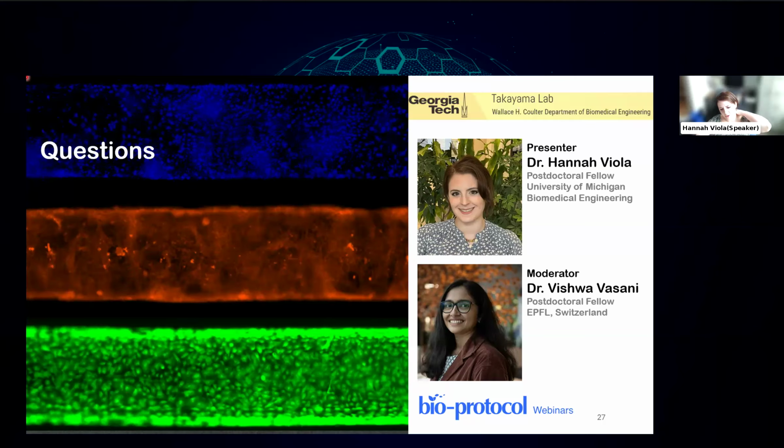Yeah. And while we're on the subject, one of the other concerns with your lubrication system is that our tools are so small that it's possible that pieces of whatever you're milling are going to get stuck in the tool. We call that clogging the flutes. While you're cutting off pieces of plastic, that can create a lot of friction, which can create heat. And that's what the air is supposed to help with: both getting rid of the chips before they can melt onto the tool and also cooling off the tool a little bit.